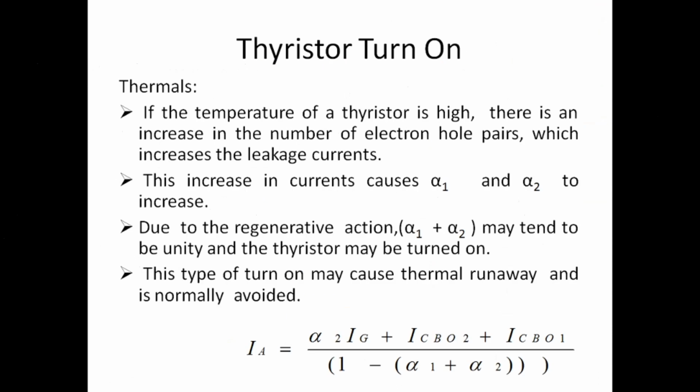So that's the reason we should make a proper cooling arrangement for an SCR, such that the temperature of the SCR should not increase. We should remove the heat from the surrounding environment, so that we do not allow the heat to diffuse to the thyristor and its temperature should not increase. That's the reason a cooling arrangement is required, it may be in terms of a heat sink or fan, and it is very much essential.